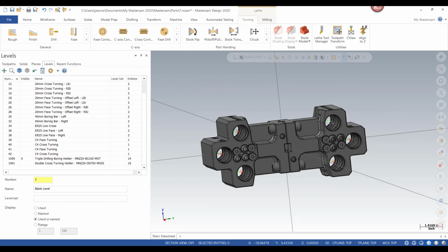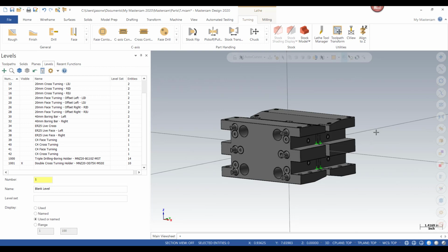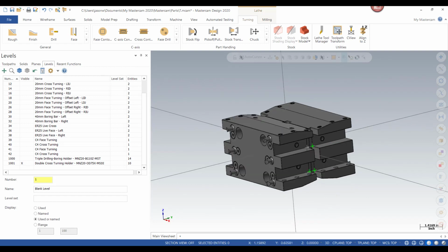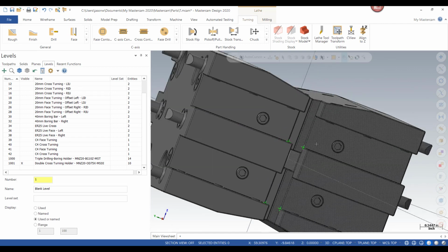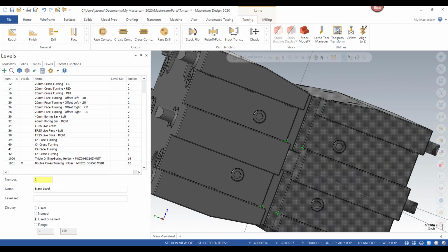Essentially, these points are 2 inches below the front face, which is a standard that I utilize across all drilling and mill tools. If we look at the other holder, this is going to be a Y-axis style turning holder. 4 different holders can be located inside one of these tool locators, and they'll have a particular orientation based on the tooling that you have at your disposal. You can also see that I've placed my points here where the tools will attach. Essentially, as we looked at before, this is towards the back of the holder.